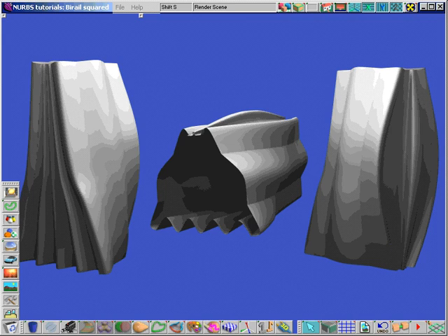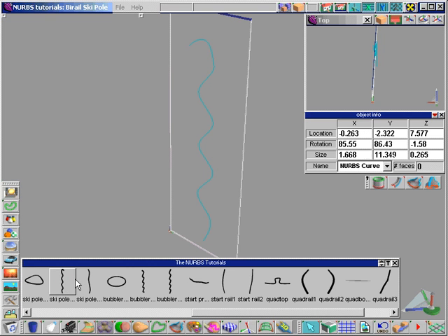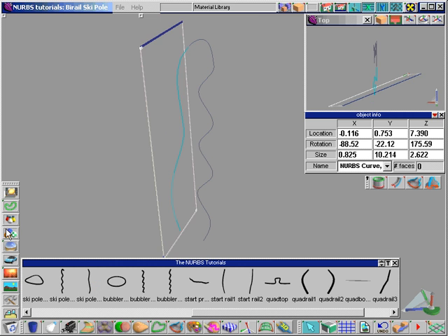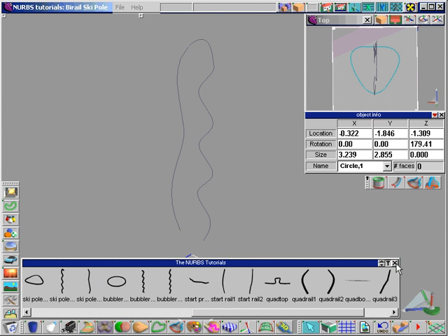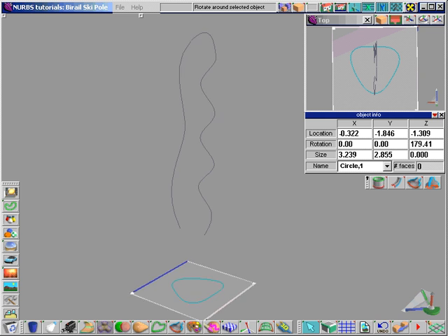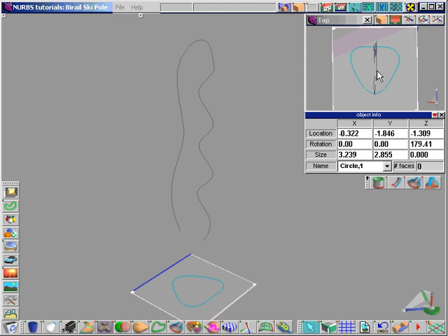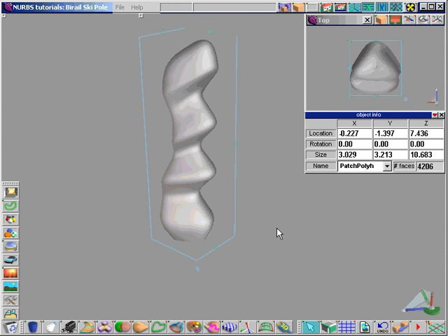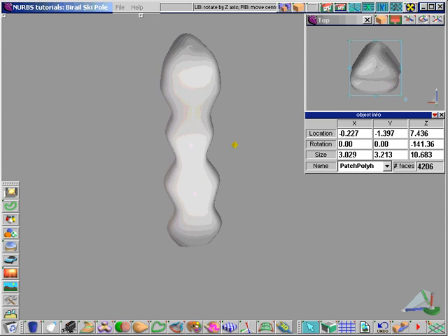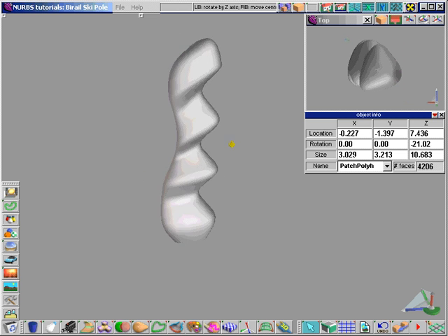In addition to creating surface components, use the birail tool to model complete objects. Here we'll make a handle grip from three simple curves. You'll recognize the first one. We've used it several times. I just edited the end of it and combined it with an S-shaped curve and a 3-point smooth polygon. This object demonstrates how you could use the birail curve edit tools to draw an object's profile in 3D.